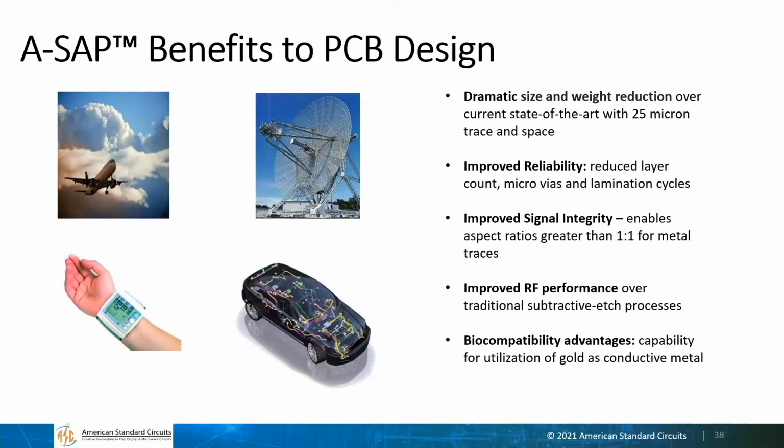Signal integrity can be improved by this. For one, if you don't need the smaller feature sizes, let's say you have a controlled impedance line, its width is set by the 50 ohms that you need and the dielectric thickness, maybe it's 250 microns wide or something. Well, this can still help because of a couple of things. One, you can get exactly a 250 micron wide line, or at least within a micron or so, with perfect sidewalls that don't change their slope.